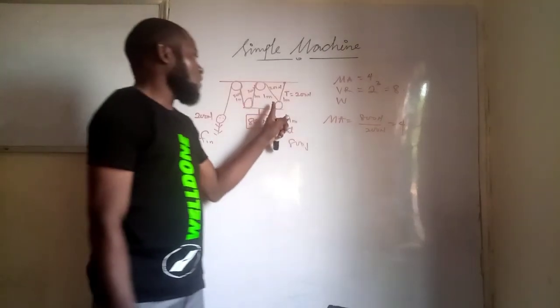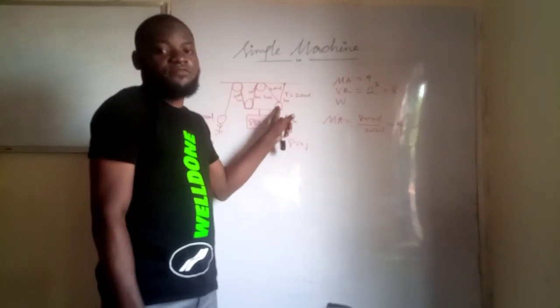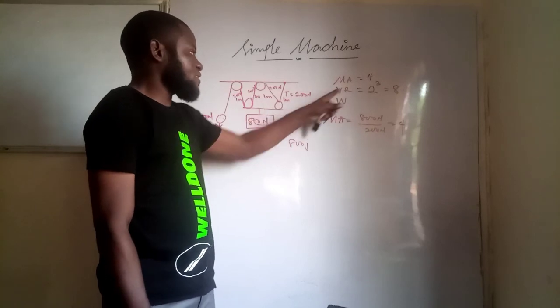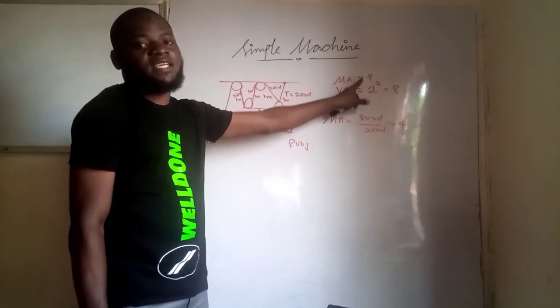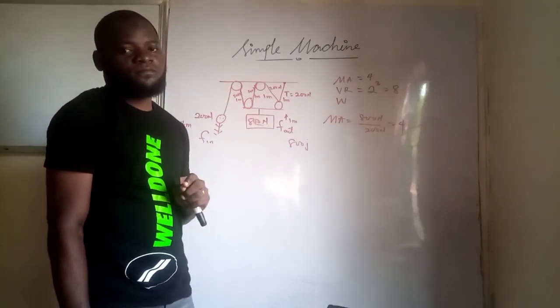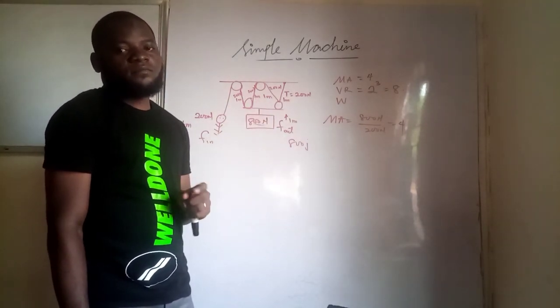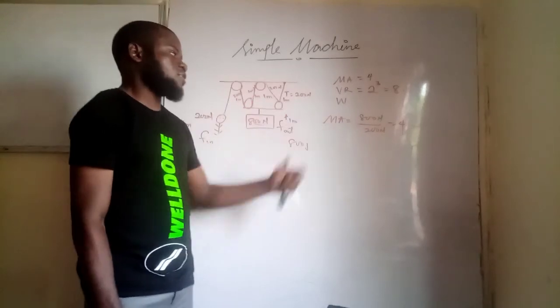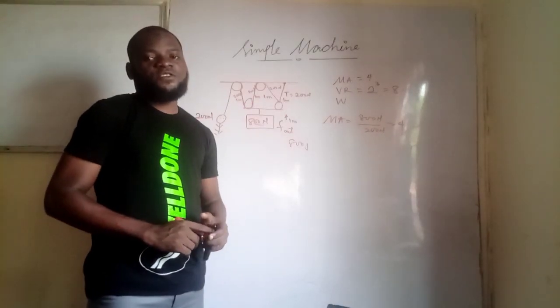Mind you, if not for considering it as a real life situation, then the velocity ratio is supposed to be the same as the mechanical advantage because there is no friction. Are we together? Cool. So, if that should be the case, we can stop the video here.